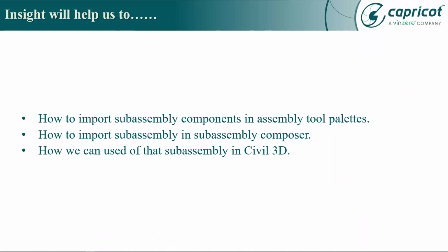The example PPT files are accessible to import into Autodesk Civil 3D and Subassembly Composer, or the program's built-in subassemblies may be customized. The same assembly may be utilized in a variety of projects and is widely used in designs, including junctions and important structures. Therefore, the current drawing or Subassembly Composer itself can export assembly data, and we can easily import the .pkt subassembly file onto the assembly tool palette.